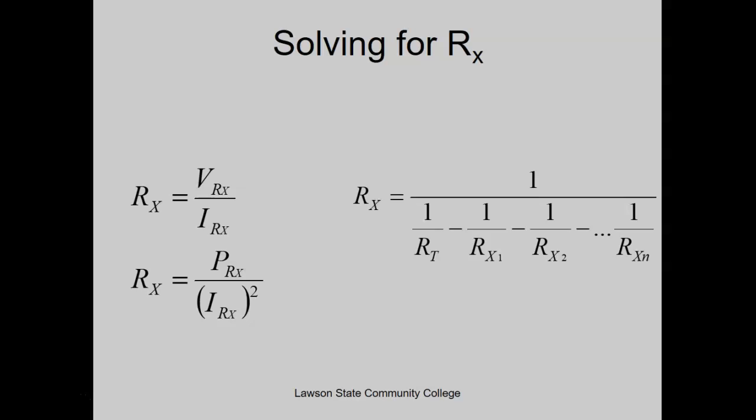So what you have here is the resistance total. Just like with series, you can subtract your resistances from your total resistance to find the resistance you're missing. Only instead of using the resistances themselves, you're using their conductance. You're just using their conductance instead of the resistance value. You just have to make one extra step on each resistor.